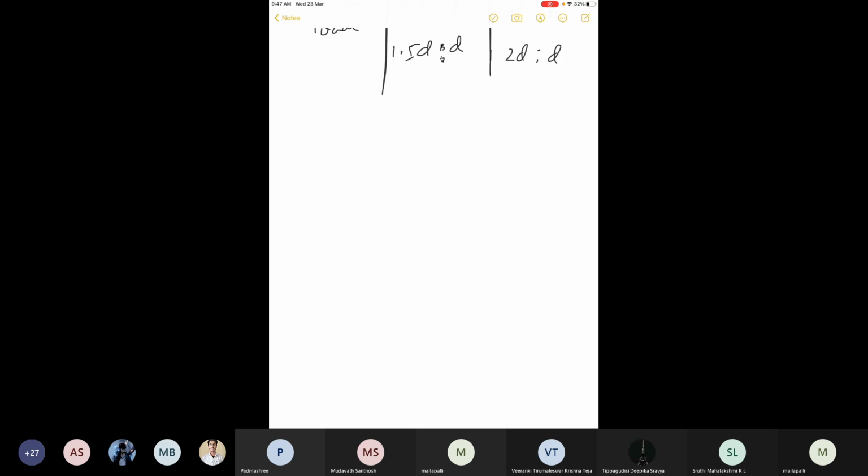Knowing the soil type, you will find the permissible velocity, Manning's n, as well as the side slopes from these two tables. With this information and the estimated Qp, you will be finding the dimensions of the particular channel. So for example, here,